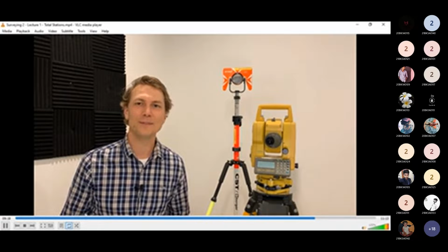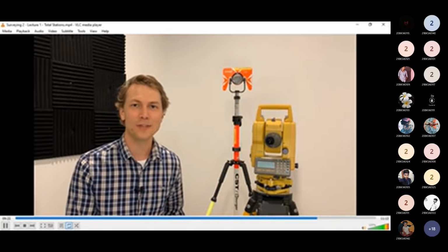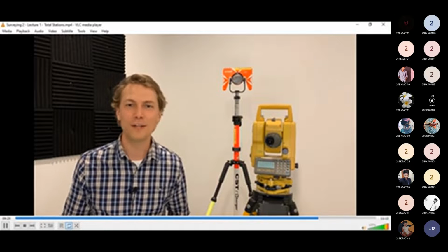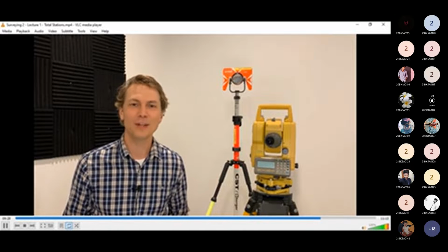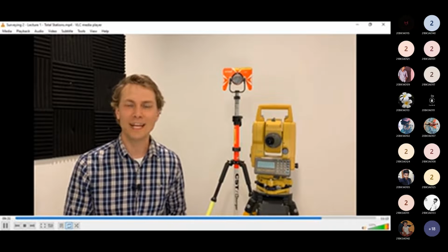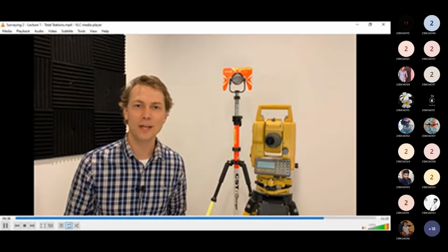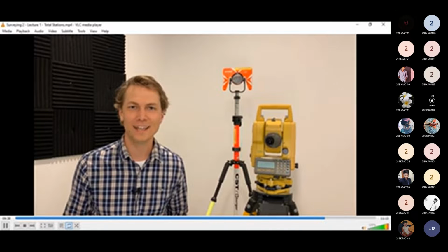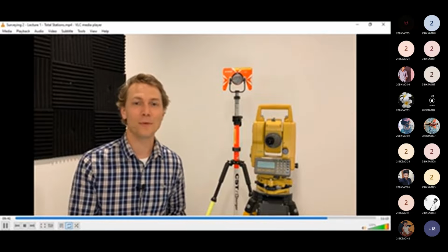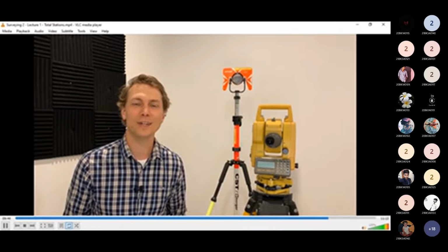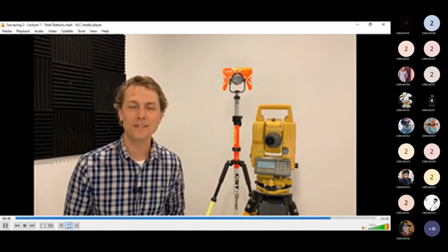The software also allows you to label each point. So you can call one point a tree as you survey a tree, and another point a, say, fire hydrant when you survey a fire hydrant, as you go through and complete your survey. You can also add lines to connect between points. So as you survey something linear as, say, a curve, you can add a line to delineate that curve and then have that information as you export into some other software package. We'll get into detail of each aspect that I've mentioned here throughout this course.